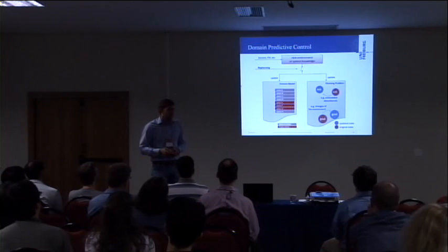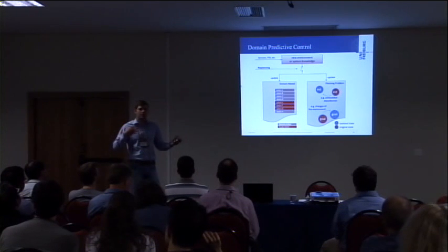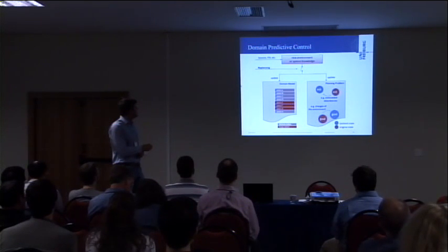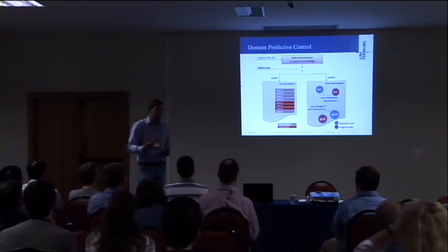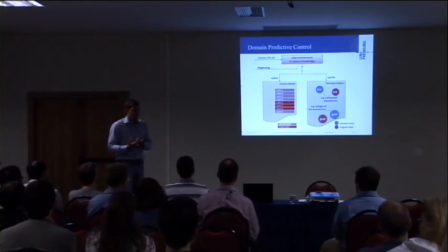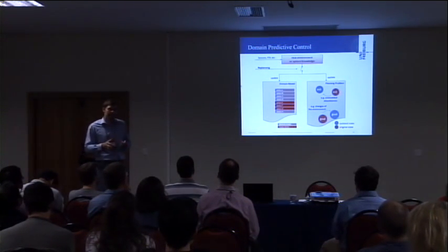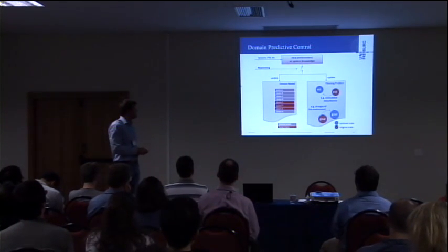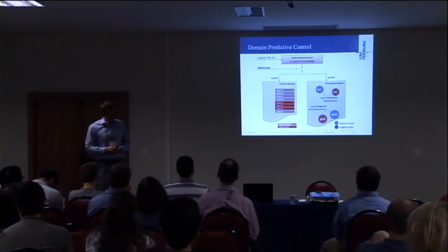In domain predictive control, let's imagine the lander receives some new information about the environment or about the system itself. At each time we replan, we can update the planning problem and the domain model. For instance, in the planning problem, the current initial state: if we are suddenly in a state where we didn't expect to be, this can easily happen if in the real world there are some dynamics which we have not modeled in the domain model. So we can update the initial state. Or we can update the goal information, for instance, if the landing site has changed.